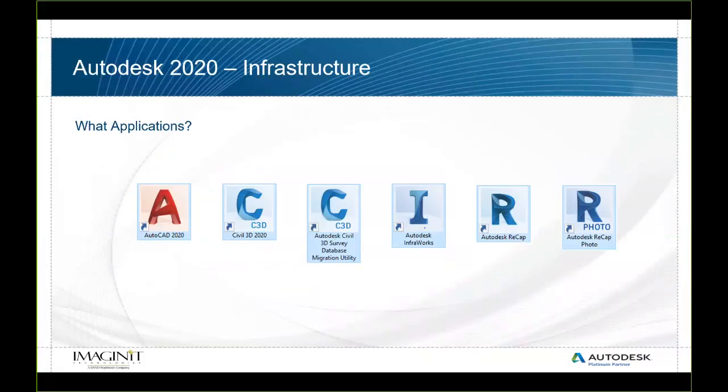So there is a Civil 3D survey database migration tool that you can use. We're going from SDVX files to SQLite databases for Civil 3D survey. So there is a tool now that allows you to migrate the old SDVX databases into the new SQL format so that you can use them in the 2020 release. That is something that you will notice there.